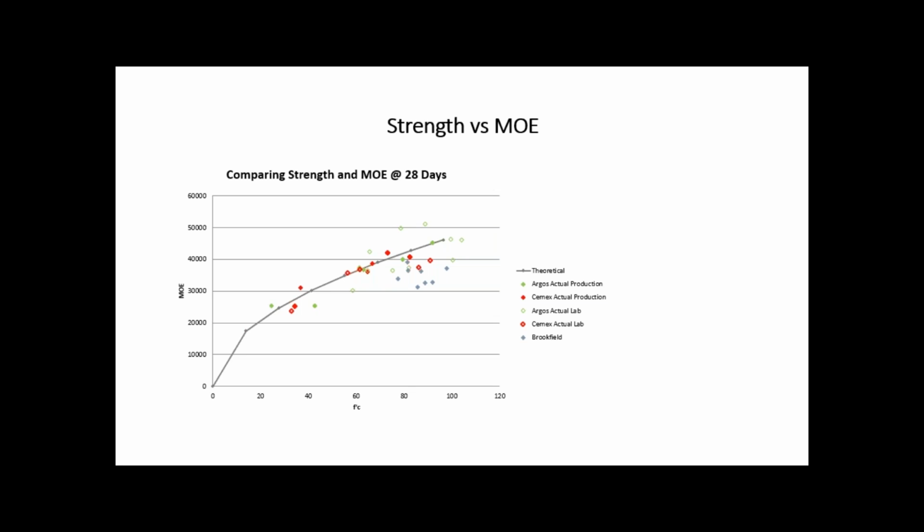Usually this is done as a pre-qualification. If you remember from the previous slide, it's the responsibility of the engineer to ensure what kind of modulus can be made. In a lot of these projects that we worked on, we did pre-qualification testing with various types of aggregates to determine what we can achieve with the basic types, and adjusted and modified to the point where we got something achievable from the requirements of the engineer.